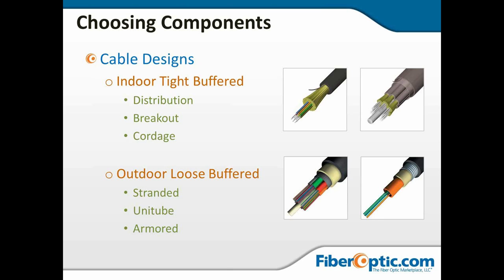So it's not just squirrels, but any kind of rodent that will chew on the cable. You want to protect your cable and your fibers inside the cable by using armor. If you're going to direct bury, you want to give yourself a little extra protection against crushing forces. If you're underground and in conduit, I wouldn't worry too much about armor.